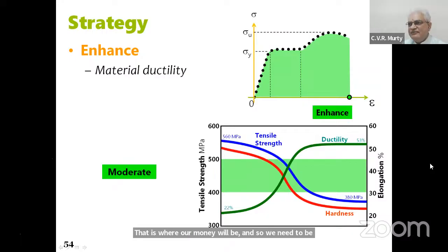How do we get careful? We need to do enough number of studies on steel as a material, steel as a section, steel as a member, and steel in a structure. All have to be put together for us to be able to say that, look, I'm confident that I can use steel of this strength, even though it has a certain level of ductility.